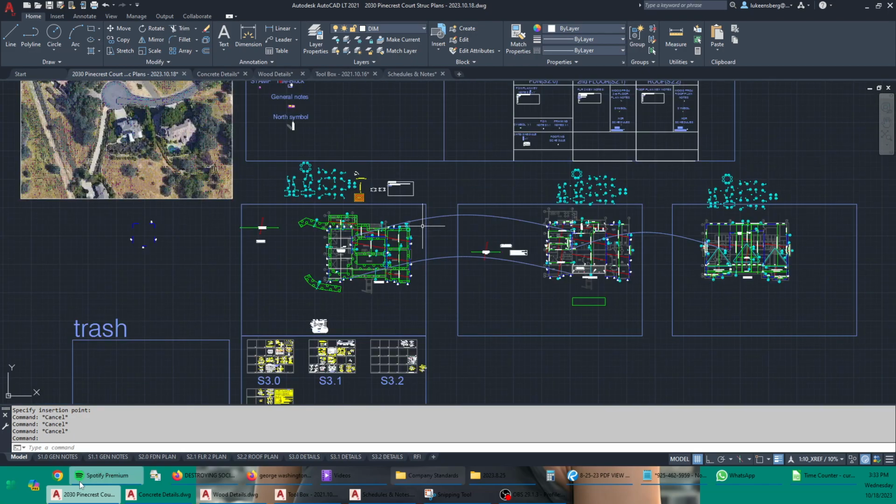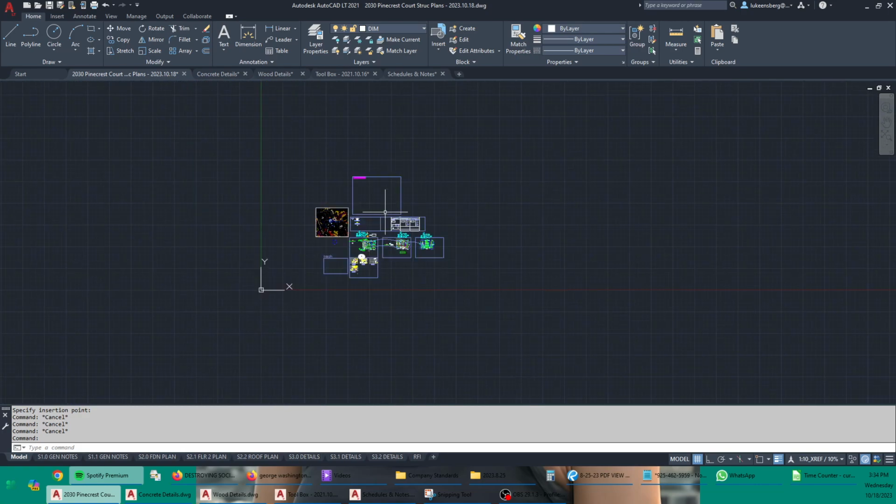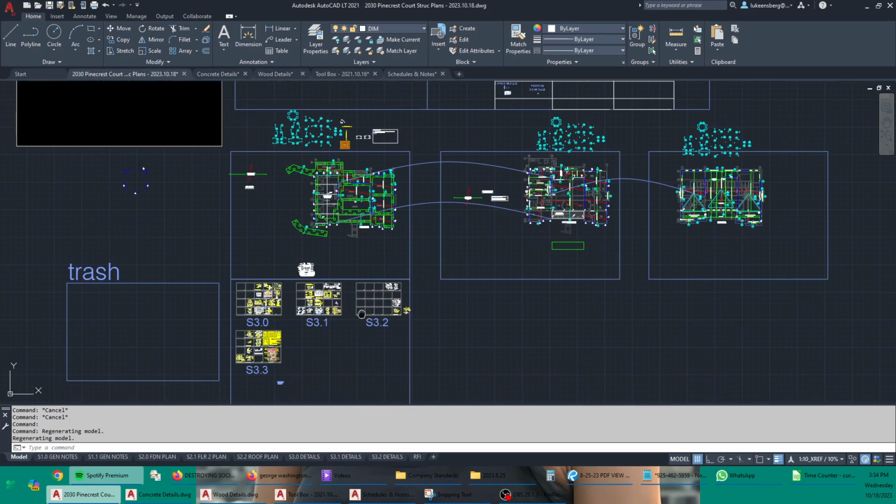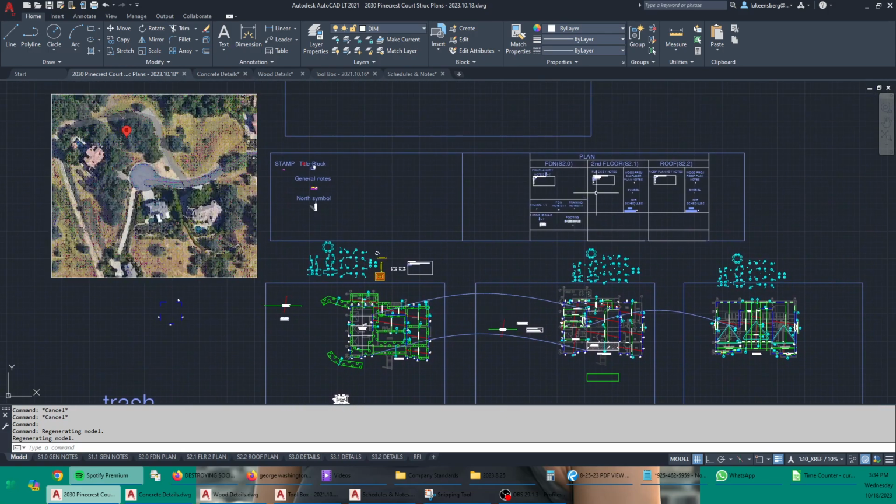Yeah, I'm going to go onto the plan view and I need a viewport in my foundation schedule. So viewporting, okay, this whole black space that I'm in is called model space. It's just a huge open void space where I could put anything I want in there. See, if I zoom out, you can see there's no limit to how much space I have. So all the things that are in my structural drawings are in model space.